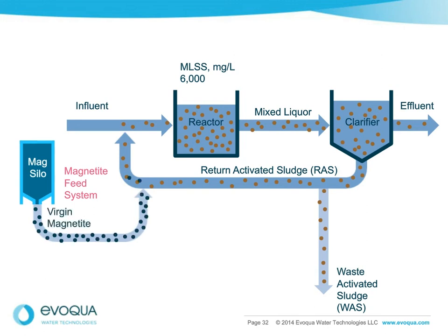and we have a feed system called a silo, and that can come in a variety of sizes depending upon the size of your activated sludge process, we ballast those solids so they settle more readily in the clarifier. You can still use your conventional RAS pumps to return mixed liquor to the front of the process. You still run the processes you normally would biologically.